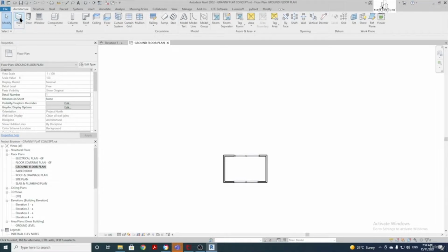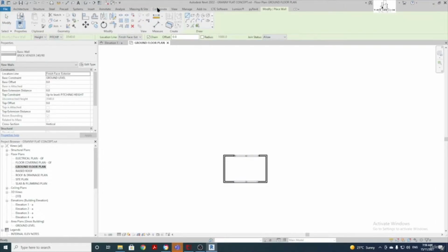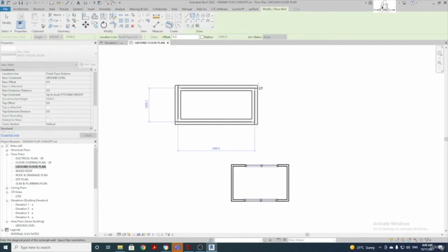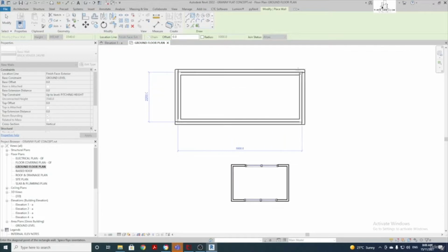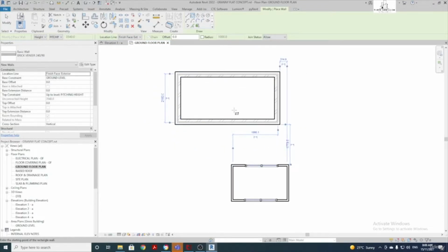Okay, come back here, click our wall tool again, and up over here on the right hand side, you'll have this little box here with different selection types. So at the moment we just had it on the line tool, which means all our walls will be drawn as lines. If you want to draw your walls as a rectangle, click on the rectangle box beside it, and this will drag out a rectangle of walls. Second click and then you'll finish your rectangle.